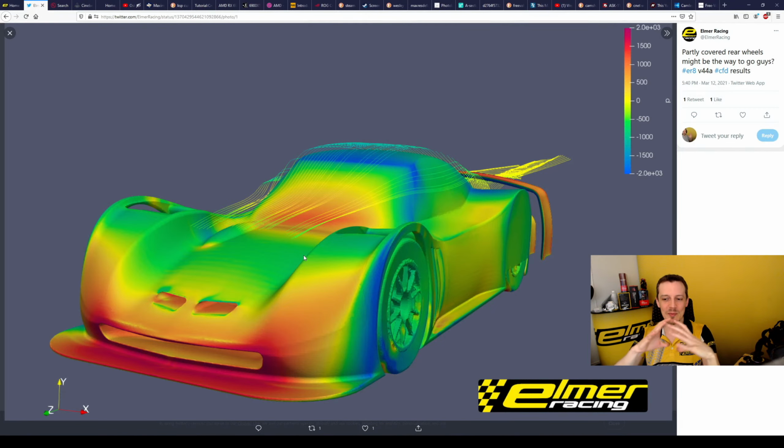So we want to package the engine bay really, really tight. That means the intake manifold, so we still want to have a good intake manifold with good intake trumpets and stuff like this, so we don't need to deal with large cylinders, and we want to have a good VE so that we have very good off-boost power in the engine. So that ends up making the plenum have a reasonably large diameter. This is basically the plenum shape, sticking out a little bit. It's not really optimized around that, but it's sort of a placeholder for the shape of the plenum.